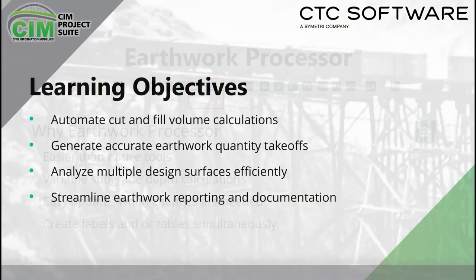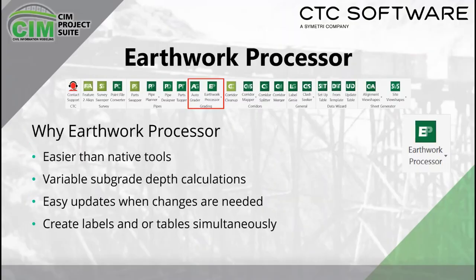So why did we create it? Why use Earthwork Processor? Well, it's easier than native tools than using the volume dashboard. We can also create variable subgrade depth calculations within our sets. And when updates are required, we can run those very easily. And with that, we can create the labels and/or tables simultaneously.